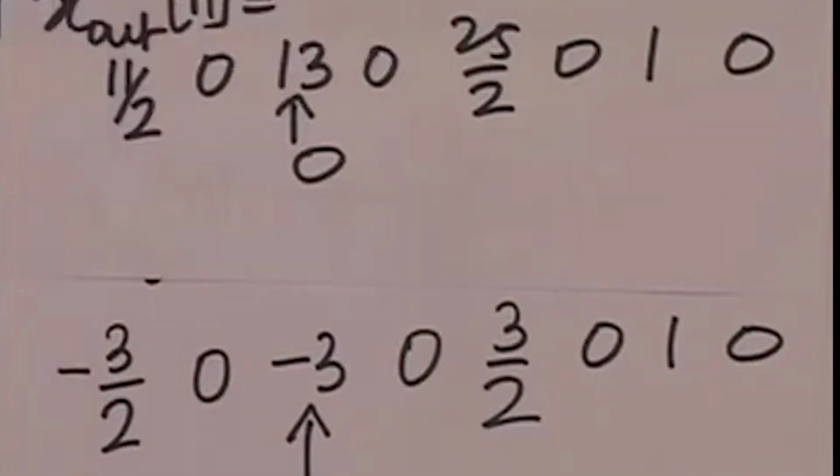Let me write this down explicitly. So, you see, it is interesting. What we are doing here, you must understand what is slightly different between the analysis and the synthesis filter banks. In the synthesis filter bank, it is as if one filter operates for one sample and the other filter operates for the next sample. And therefore, you could visualize a situation where you carry out both the filtering operations at once, but then allow the sample from the upper filter to pass in one instance and the sample from the lower filter to pass in the next instance and keep alternating in this way.